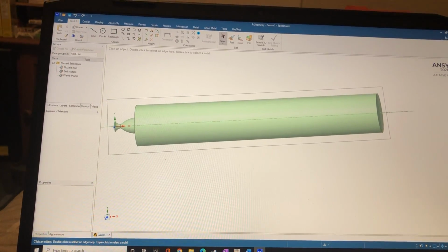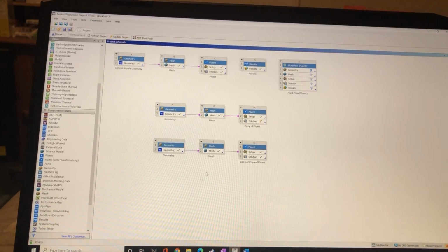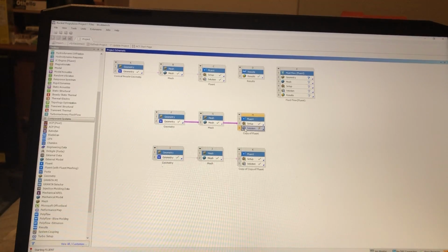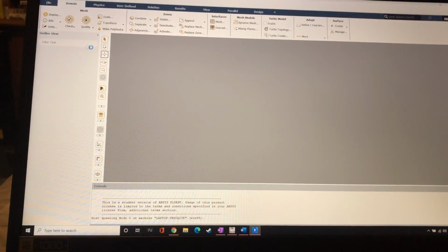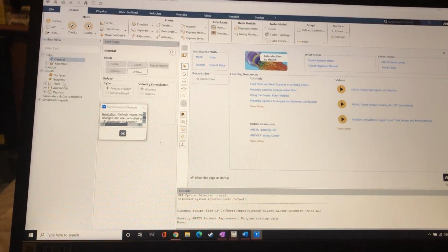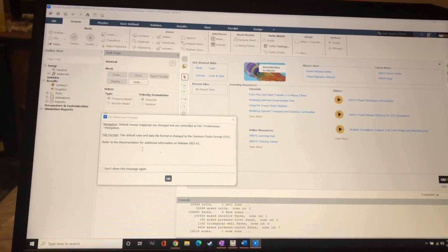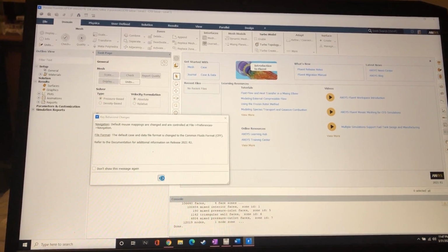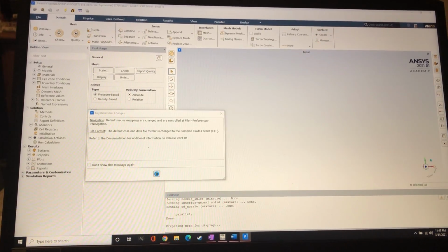I will show you my simulation data, though, if we can get into there. I did the same sort of steps: activate the energy balance, K epsilon behavior of the gas, setting the boundary conditions. All of that was exactly the same as the previous example.